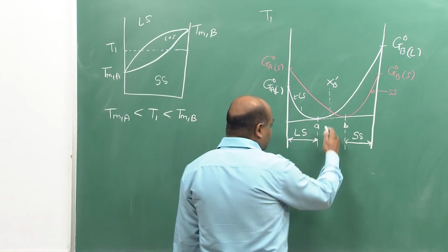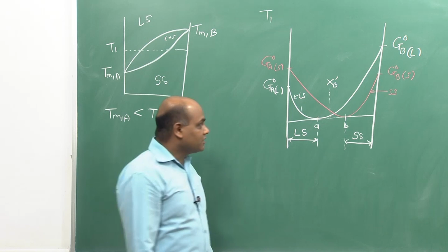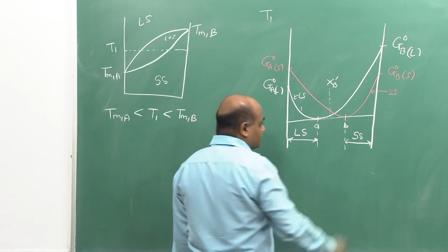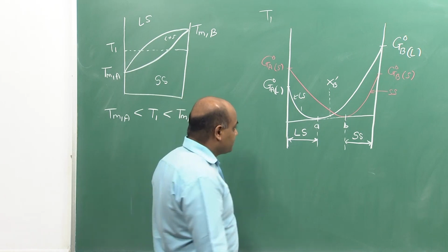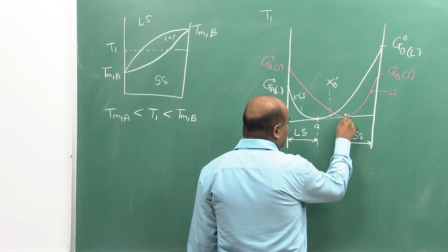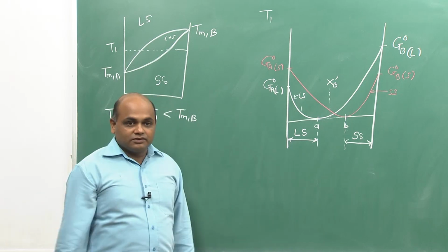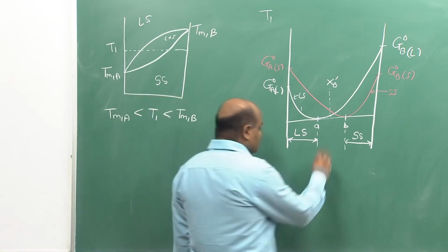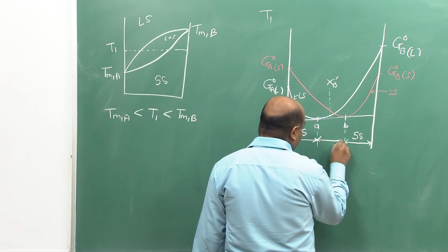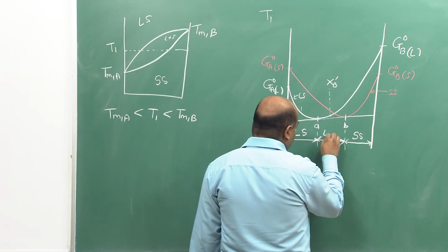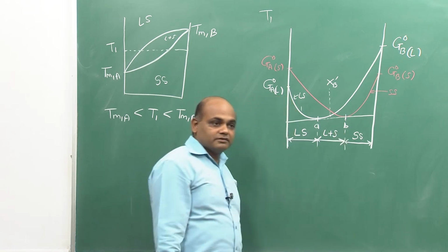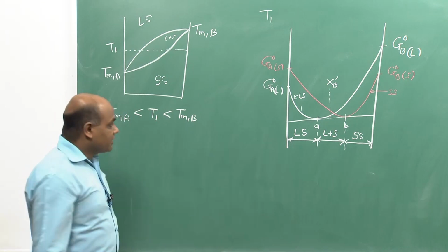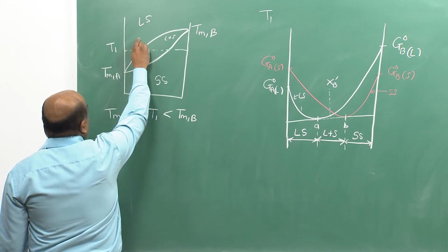and by doing this we can decrease the Gibbs free energy, and so the one composition will split into liquid solution and solid solution, and the equilibrium compositions can be marked by the common tangent to the two curves, A and B. So, for any composition between A and B, there is a two phase equilibrium, liquid plus solid, and these A and B can be marked on this phase diagram here, right.